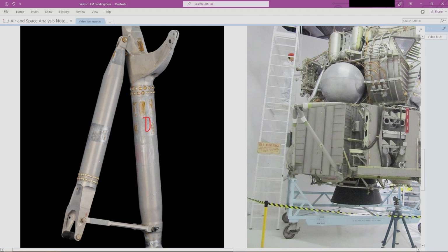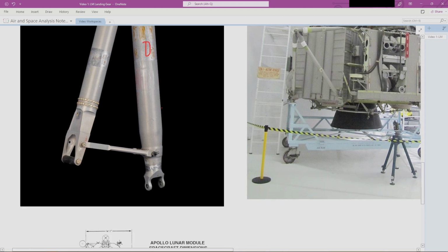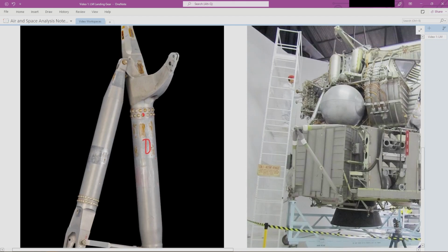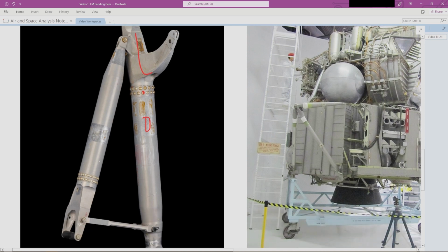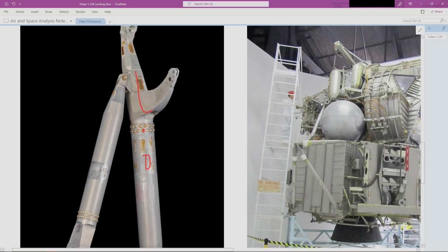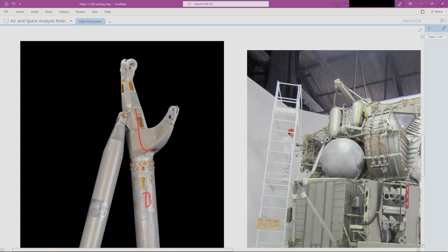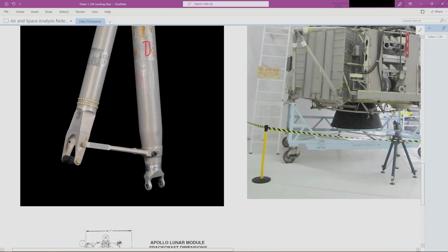This will be a hollow tube. These are rivets. And then over here, they actually have a welded connection. This is a machined part, right? And then this is another tube, machined part, rivets, probably welded on somewhere in here, but they might have just ground or sanded down the welds so that you can't see it, but they left it over here.